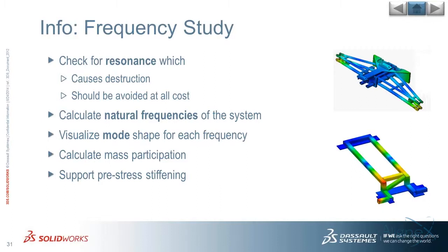And if we check our frequency study, we can get the first natural frequency values, and we can design our assembly in such a way that the first natural frequency is much higher than those dangerous frequencies for your environment.